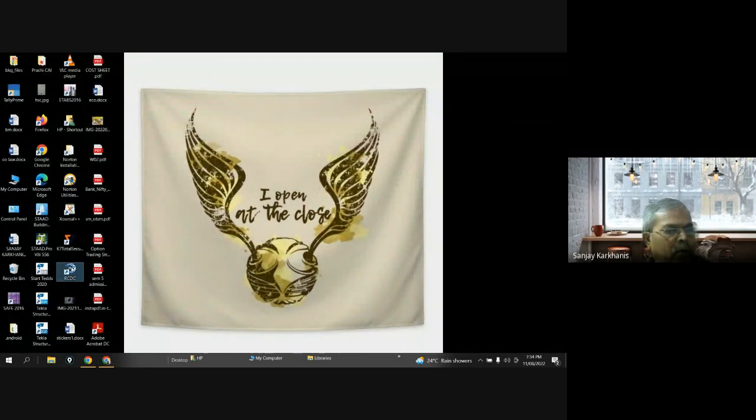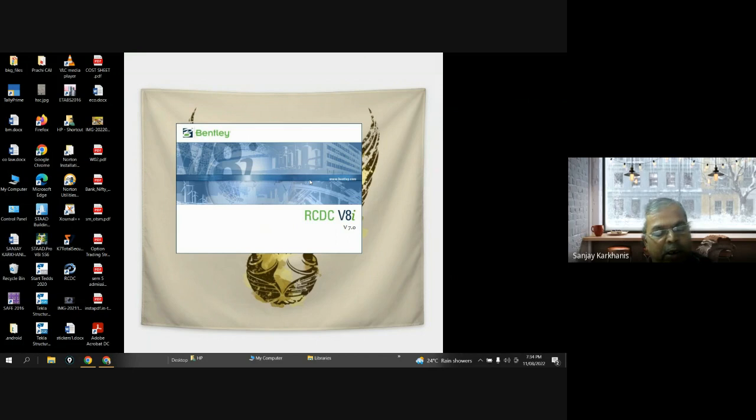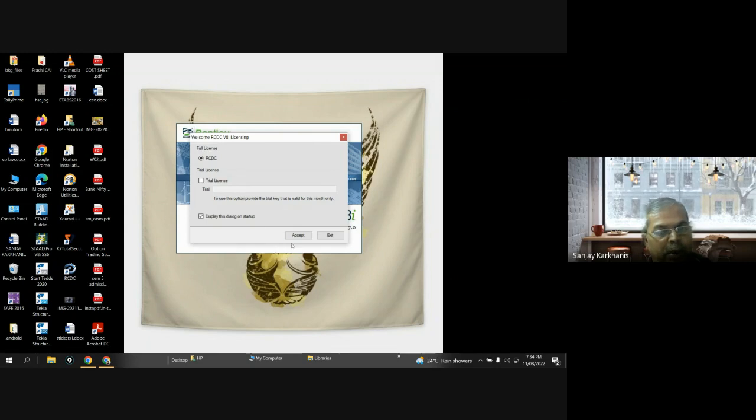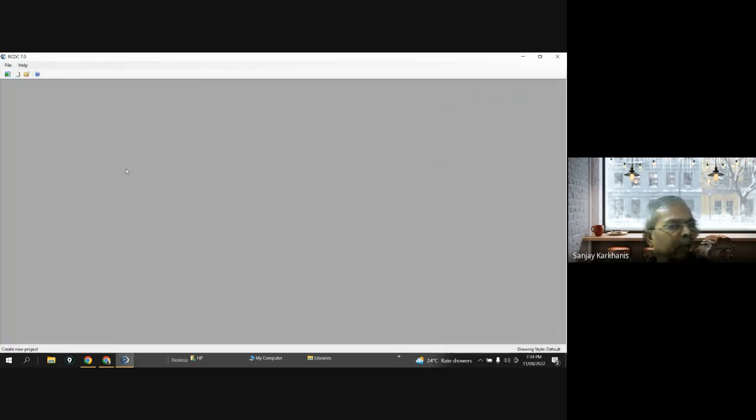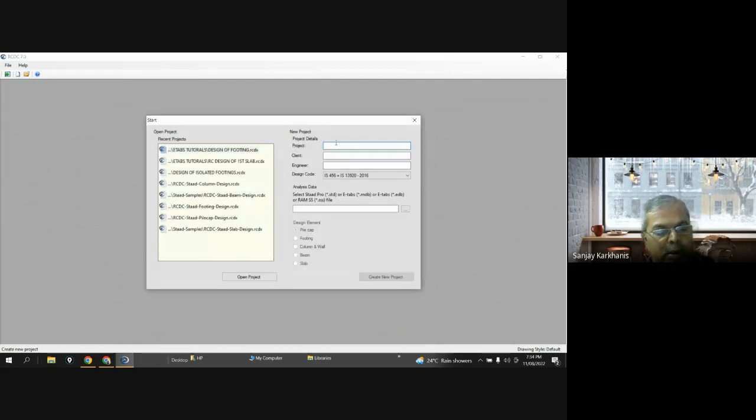Straight away we'll go to our RCDC. Now we don't have to go for preparation of that MDB file again because we have imported all data. So straight away we will open RCDC and we'll see that. Maybe batch 20, project say residential column design. We'll say column design.